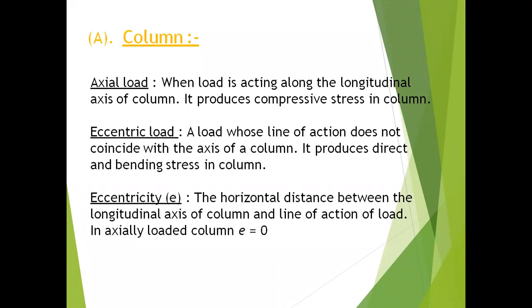Inka, rafter. Okay, which rafter? Top rafter or bottom rafter? In a truss, which rafter will be subjected to compression, top or bottom? Bottom. See, the rafter is a top member which is a compression member, the bottom chord is a tension member. Okay, right. So that is also a strut, but technically we call it a rafter.